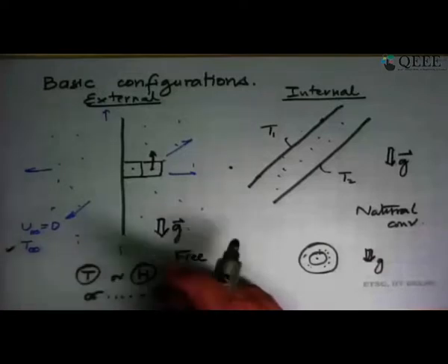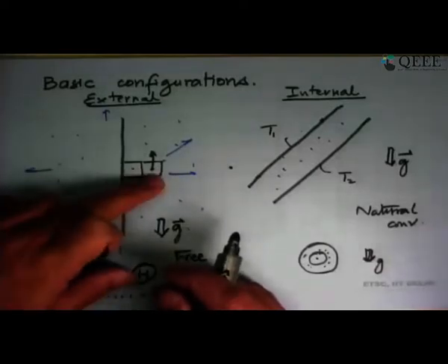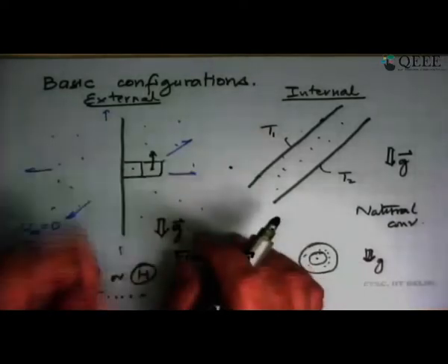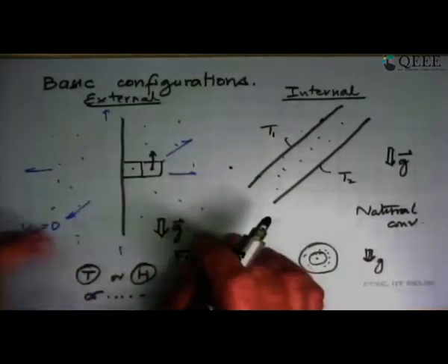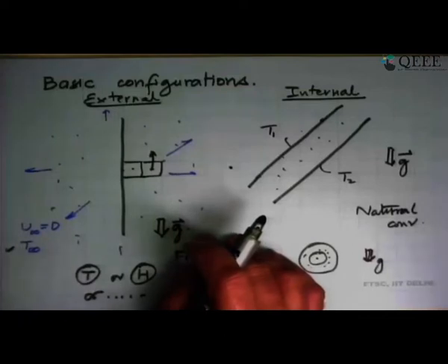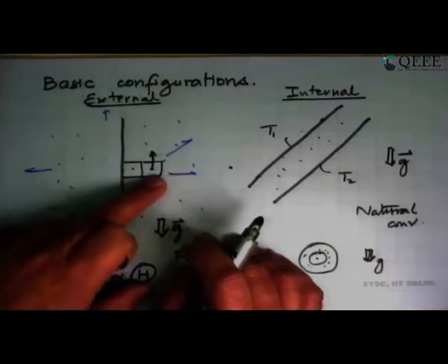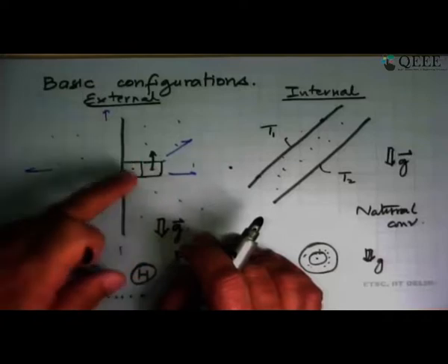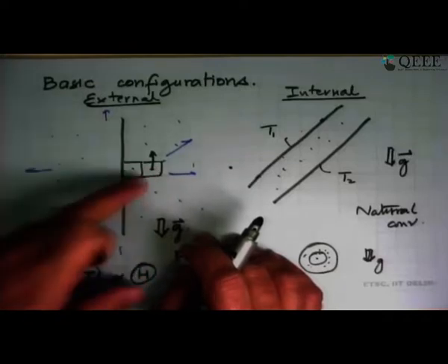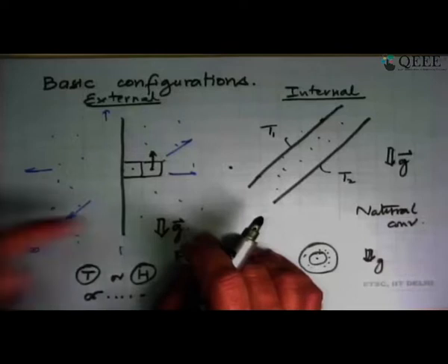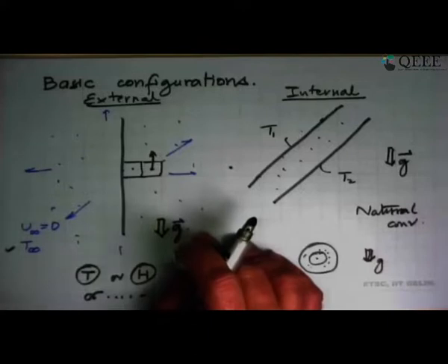That is the fundamental phenomenon of natural convection: it is the temperature difference within the fluid which causes the fluid to flow. So in some sense, this is an extreme case where there is no forced flow on the plate, because when we were looking at forced flow on the plate, we did have temperature gradients in those fluid elements also, but we said that this phenomenon in forced convection is very weak compared to buoyancy, and so we neglected buoyancy in all the discussion of forced convection. So that was an extreme case where the temperature-induced body forces were negligible.